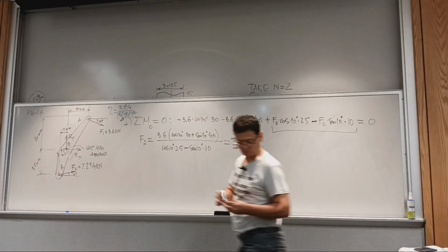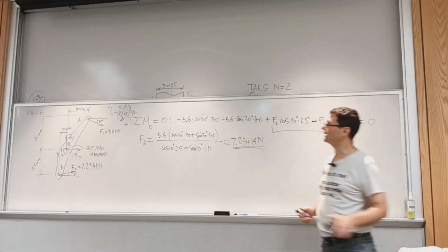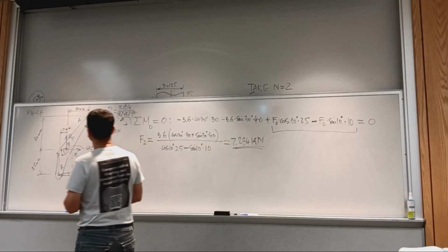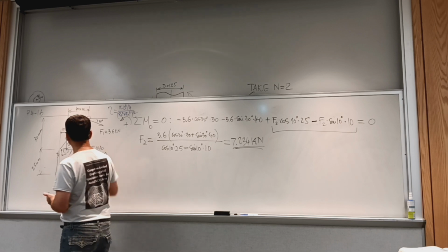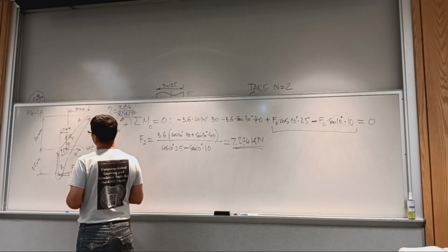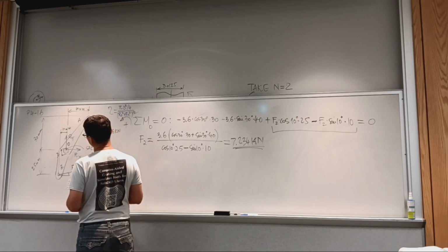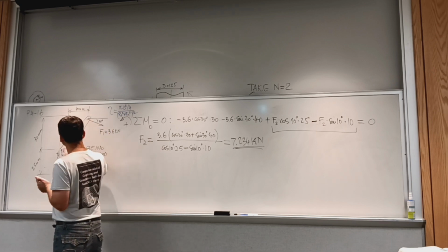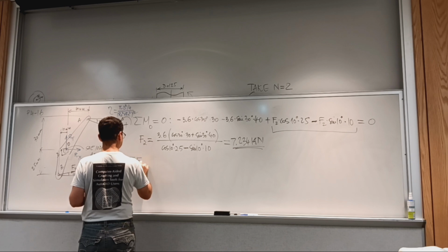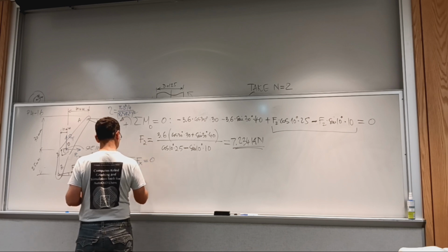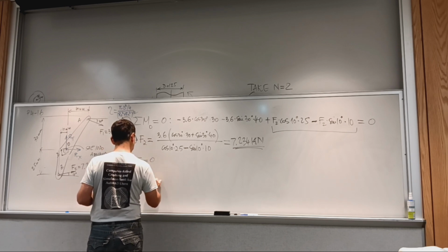That's the formula that we're going to apply. So this is a lot of statics, or more statics than the new stuff. Okay, so in order to get the reactions of the support, we can sum moments. I don't see a benefit. Let's sum forces in the y direction and x direction, sum of forces equals 0.